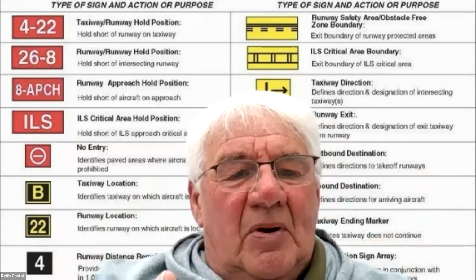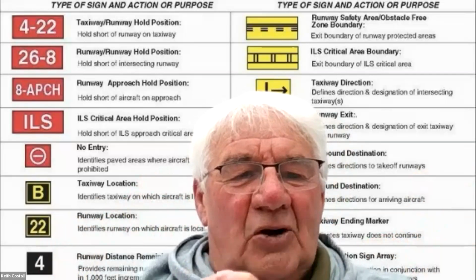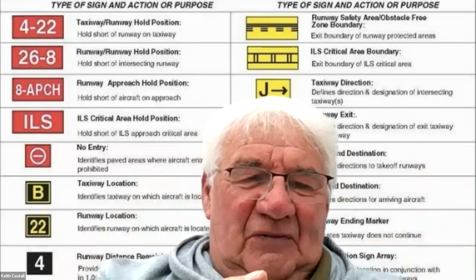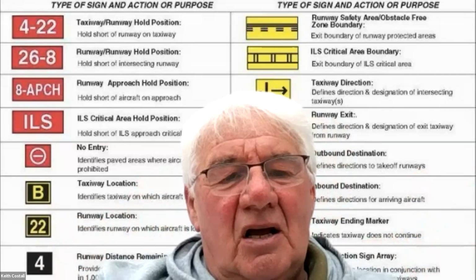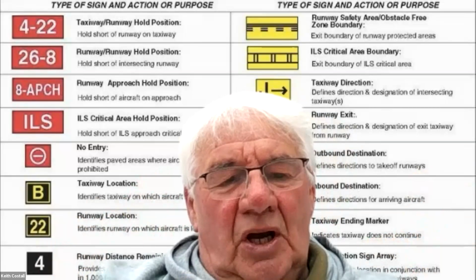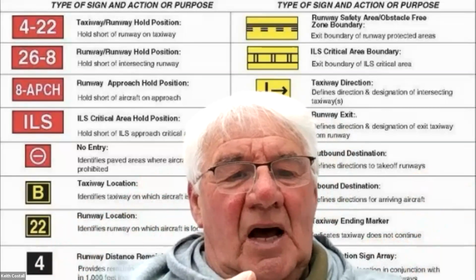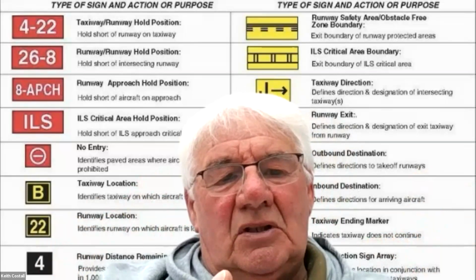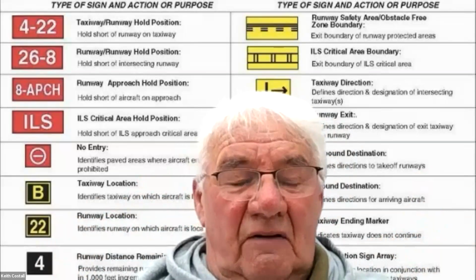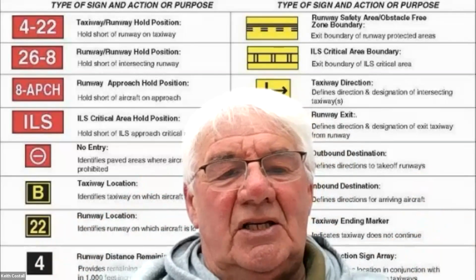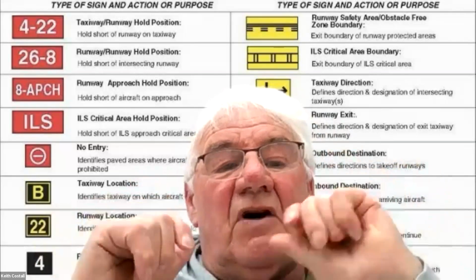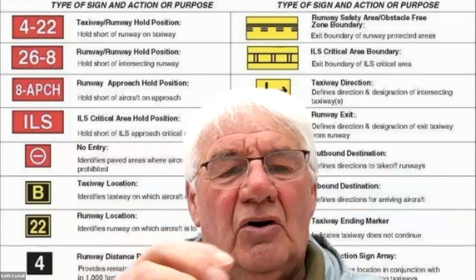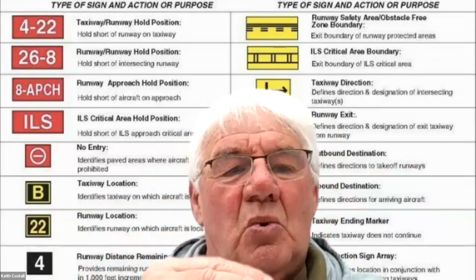But when it comes to the PAPI, and it's interesting, Tony, you may have an input on this, please. The tolerances for the PAPI, because when we're measuring the PAPI and we're looking at the transition zone, and we know that when we set up a PAPI out in the field, then we give a tolerance associated with the 3 minutes of arc for the transition zone. We give a tolerance of a half a minute either way.